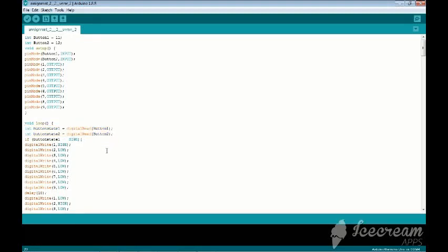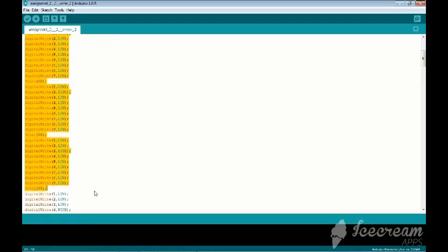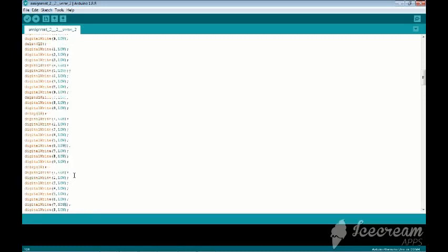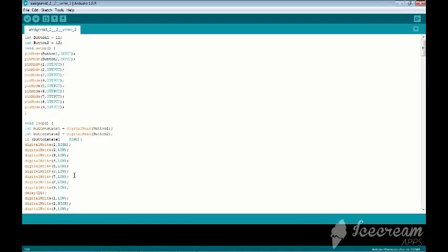Now, going through the if statement, firstly, if button 1 provides a 5-volt input for the Arduino board, or is sensed as high, all the code within the curly braces will be executed. To be more detailed, the Arduino board will execute an output from the digitalWrite instruction where the LED is connected to the pin number.